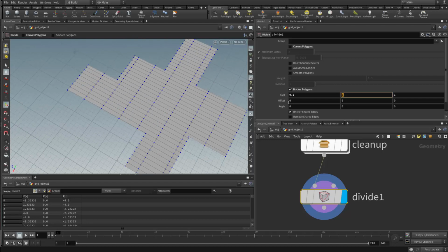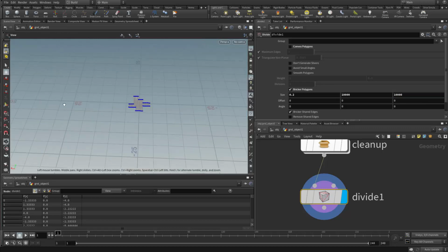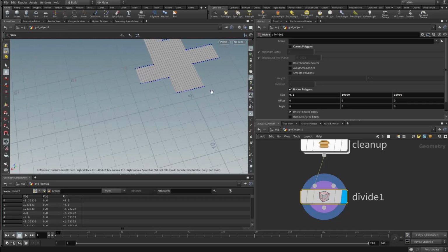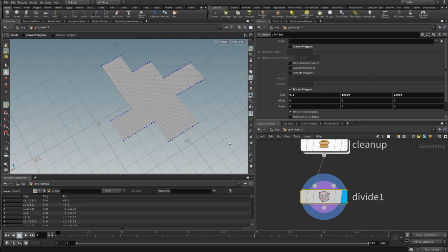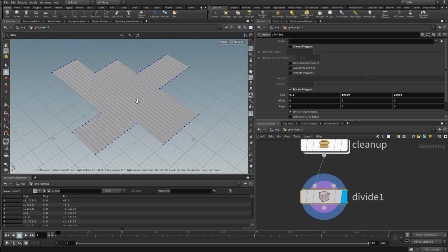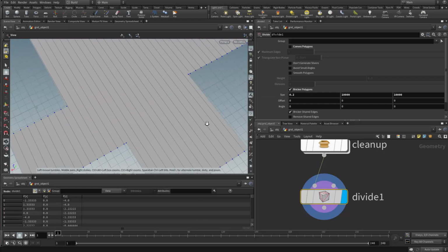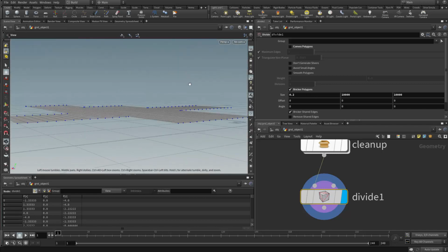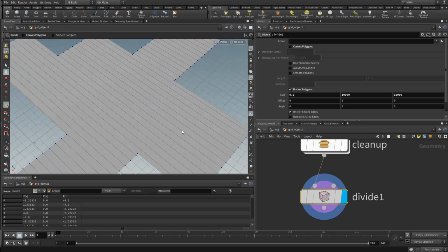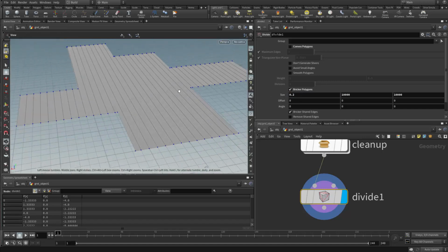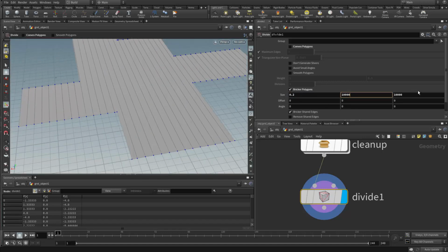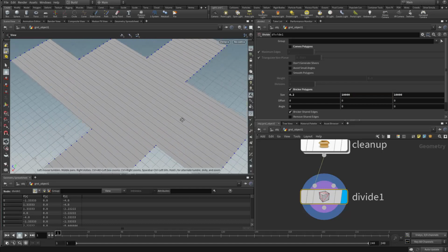For the other 2 directions, I don't want to cut, so I'm going to change it to something real big. That just basically means that it's trying to cut a big chunk, which will cut nothing because nothing is that big. Okay, cool. The unit here is that in the default settings, 1 unit is 1 meter, so that's why we don't have to worry about this big number. It shouldn't in any case cause a problem.